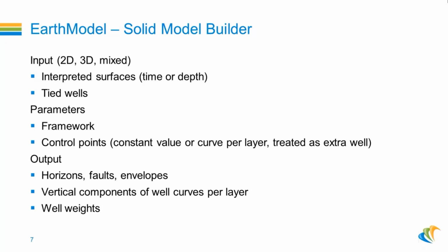And then as you build your framework, you can fill the framework with your well log information and control points. You don't need wells. You can put in extra control points per layer, and they're treated as an extra well. And as an output, you get horizons, faults, envelopes, and the vertical components of your well curves and your control points and well weights.